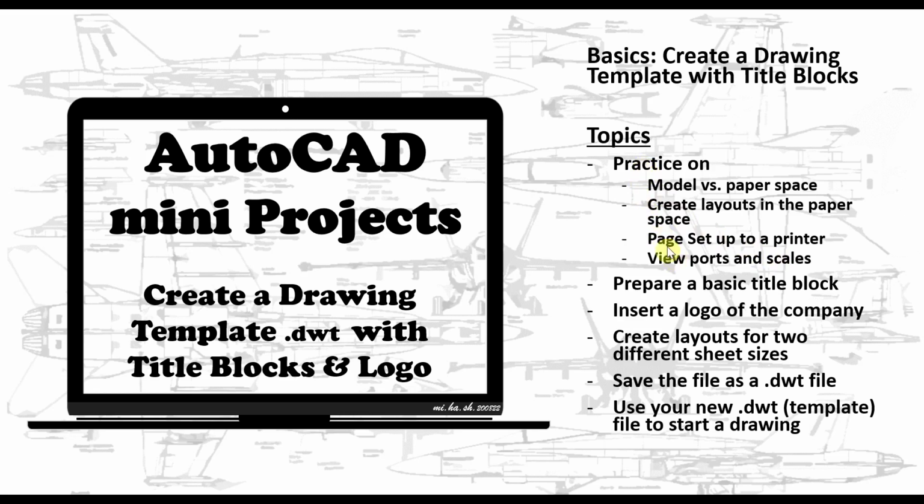So we're going to review on all that, as well as prepare a basic title block, insert the logo of the company, create layouts for two different sheet sizes with the same title block. We're going to save what you have as a DWT file, as a drawing template file, so that you can reuse it in your future drawings.